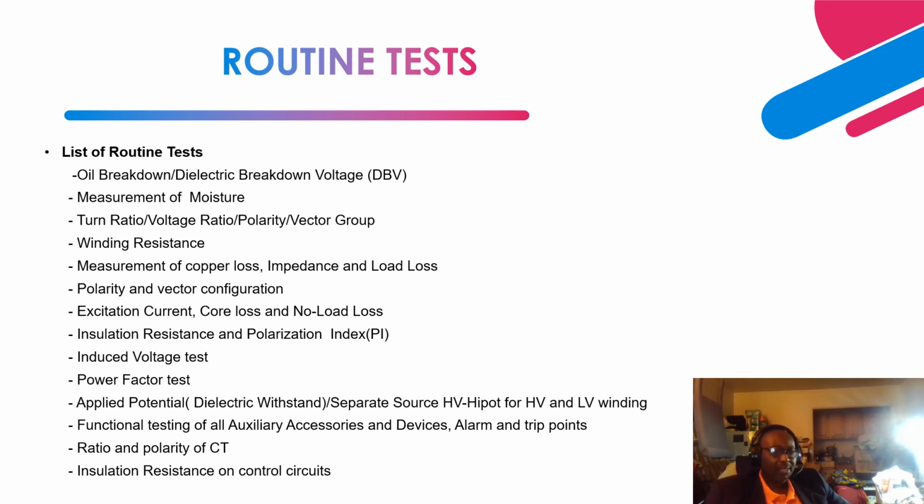As you can see here, let's say you have a DYN1 power transformer. DYN1 means the high voltage winding is in a delta configuration, and the low voltage winding is a Y with the neutral grounded. The 1 means the phase shift between the high voltage and the low voltage is 30 degrees. The 1 is a representation of the clock system, so between 12 o'clock and 1 o'clock is 30 degrees. It means that the high voltage winding is leading the low voltage winding by 30 degrees.